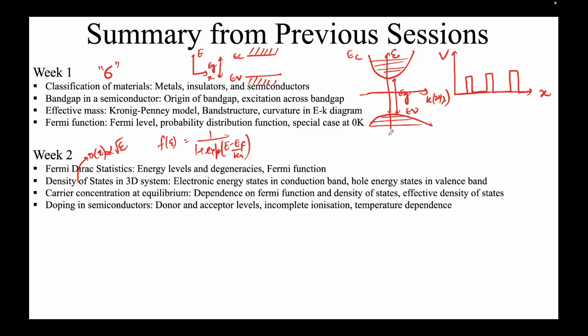So see, essentially this is a system. The Fermi level, as it happens, also exists in metals, right? There the Fermi level definition is the highest energy level that is occupied. In the semiconductor world, we tweak the definition and we say, okay, the Fermi level is that hypothetical energy level at which the probability of occupation is half. We define it in such a fashion. It's not that it exists physically. You will not find, okay, a Fermi level lying 0.7 eV below the conduction band.